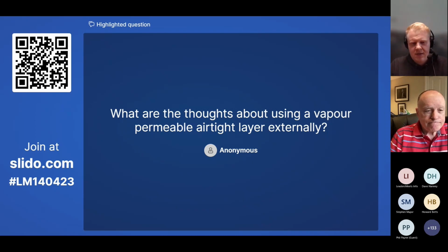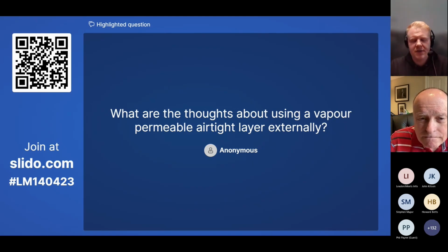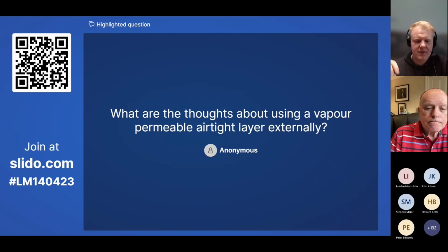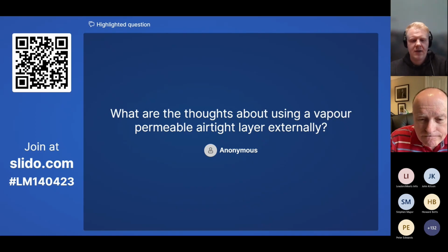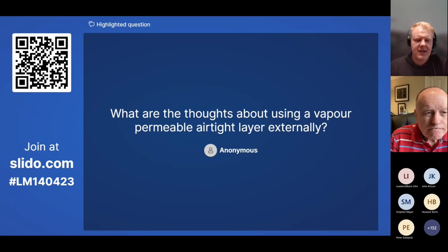I would differentiate between airtight and vapor permeable. Generally, our kind of membrane is in its way airtight, applied correctly, so sealed properly. Regarding the vapor, you could also use a different kind of membrane on the outside, but generally how we build, we have a humid, warmer inside than on the outside. You're trying to avoid having the vapor or the humidity passing through to the outside and condensating in the wall itself, in the buildup.